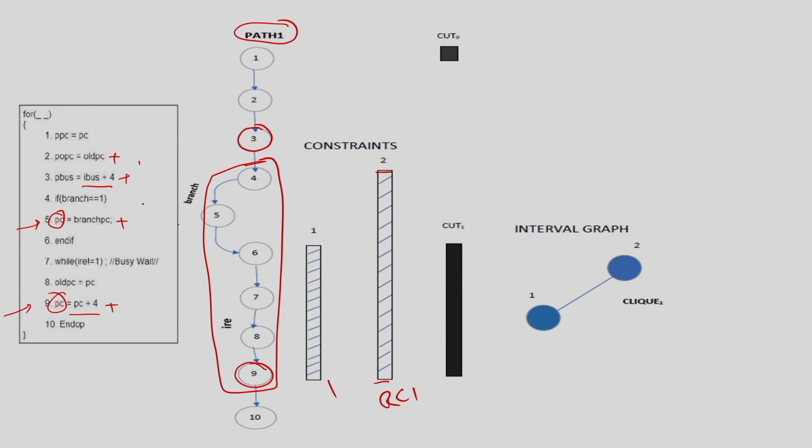So, I am going to take a path, the longest path, and I identify 3 kinds of constraints. The first constraint is the variable constraint. Is there any variable getting redefined? You break it in between. Is there any resource constraint, any long path which is not satisfying my resource requirement? So, you break it in between. And also, do you have any timing violation? There is a chain of operations; is it violating my timing constraint? Then you break it, and you break it in all possible ways so that it actually satisfies my timing constraint, right.